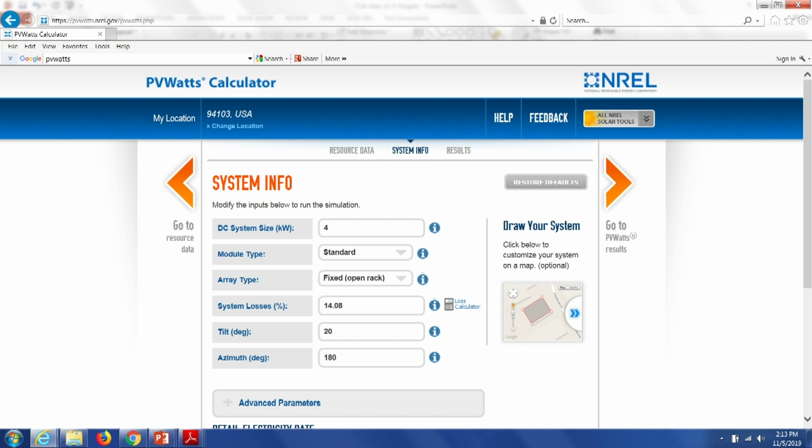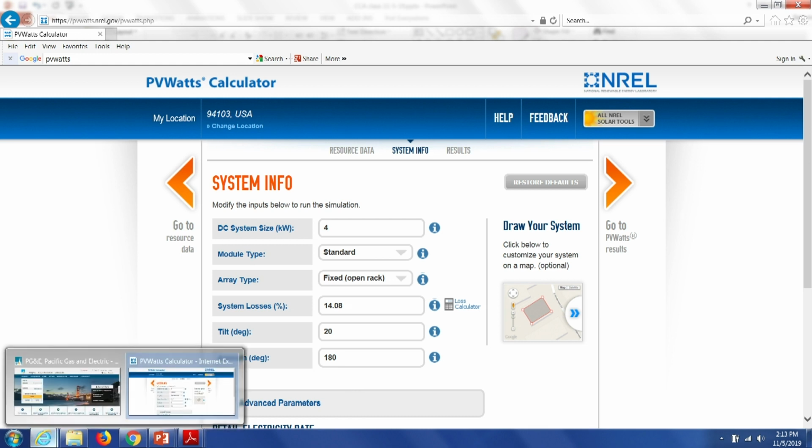One thing I want to let you know, remember I talked about azimuth and tilt here? That azimuth is 180. What does that mean? Where are those modules pointing with a 180 azimuth? Due south, right? So we'll assume that, but this is typically on a flat commercial roof.